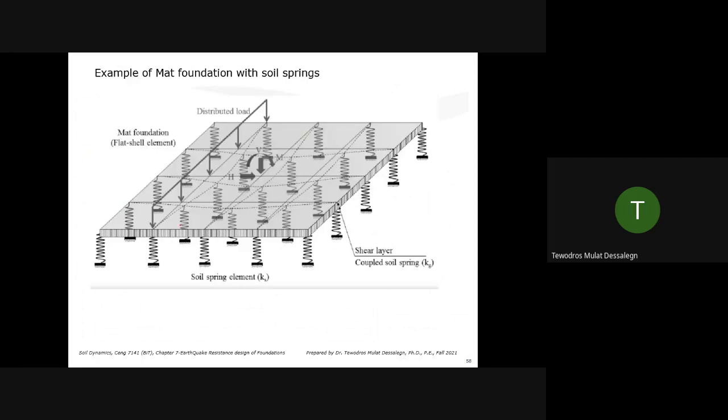And finally, this is how the final model looks, at least from a geotechnical perspective. You can have distributed springs that you developed considering the site condition. Let's say you are analyzing a mat foundation, and you have the forces from the superstructure, static forces, wind or seismic, all included.